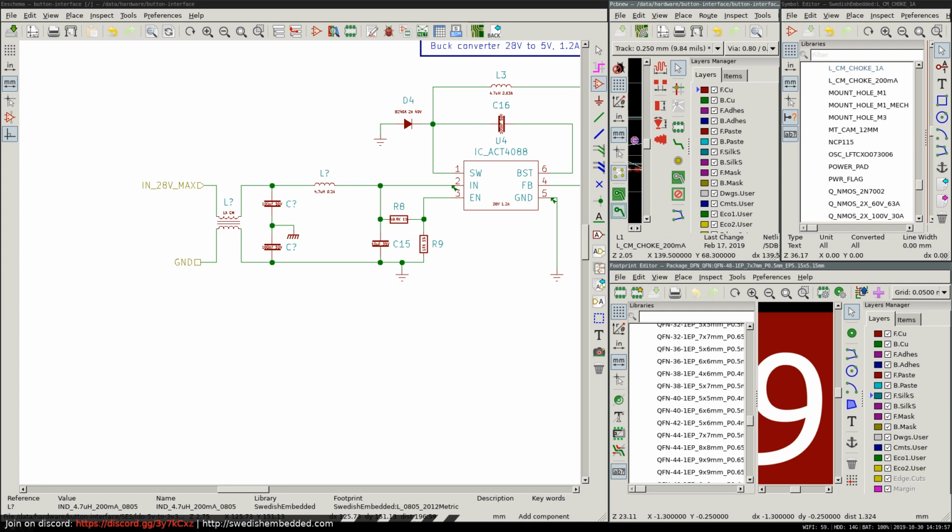Okay, so I can place a capacitor here then, and obviously I should be calculating this, but right now I'm not. And this forms another LC filter, which would be for the purpose of filtering differential mode noise. So if there is a signal here that is noisy and the ground is at 0, then we'll be filtering that signal. Now, there's another thing here: these two lines need to be balanced. So we should divide this coil by 2, and then place another coil here, which is half of the inductance.